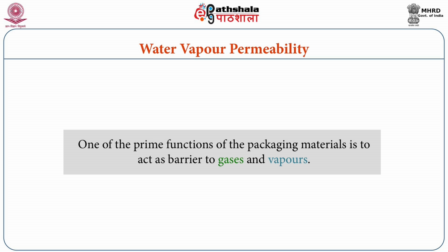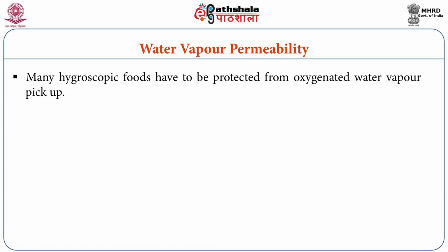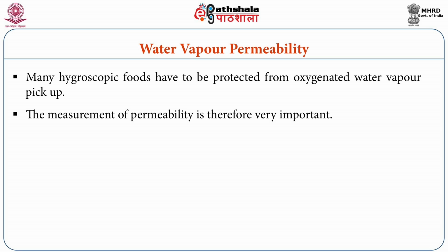Water vapor permeability. It is a very important test and one of the prime functions of packaging material is to act as a barrier to gases and vapors. Many hygroscopic foods like milk powders have to be protected from water vapor pickup. The measurement of permeability is therefore very important.